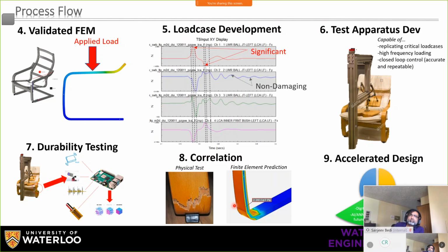Okay, and the bench might have asymmetric loading. It might have a more severe load case. Or let's say we want to dampen these oscillations here? Because someone might spill the beverage they're holding in their hand if the chair oscillates when they sit in the chair. Okay, so instead of approaching this from a structural perspective, where we want to minimize the stresses and the strains in the parts of the design that might fail, we might want to increase the stiffness of the chair so that it doesn't oscillate as much.